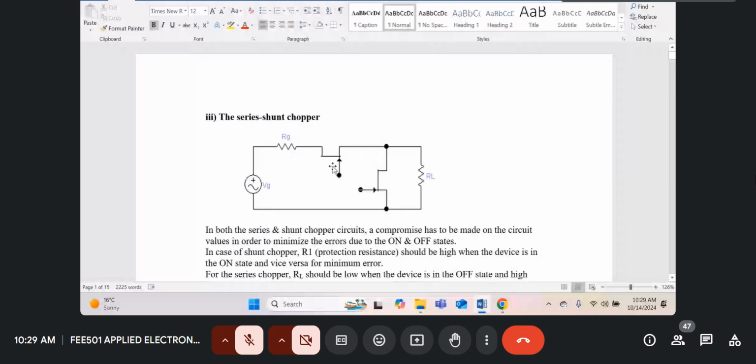Now you can put it in the same table, use the same level of signal VG, and then find out the on error and the off error, and therefore we can make a decision as to which switch configuration we should use to give us the least error.